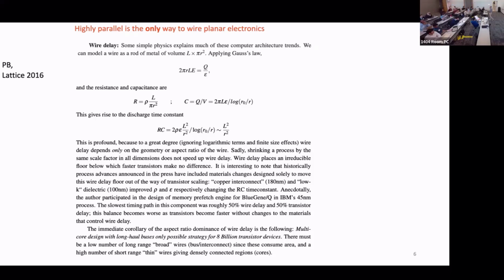Right? 2 dimensions is better. 3 dimensions, the mean distance you would have to drive would be a lot smaller again, right? And here, potentially the way to keep RC delay or wire delay long term is to go to 3D logic, right? Because you will reduce the mean wire length in a chip and not be stuck in these planar structures. And planar structures are a lot better than one-dimensional structures I have discovered.